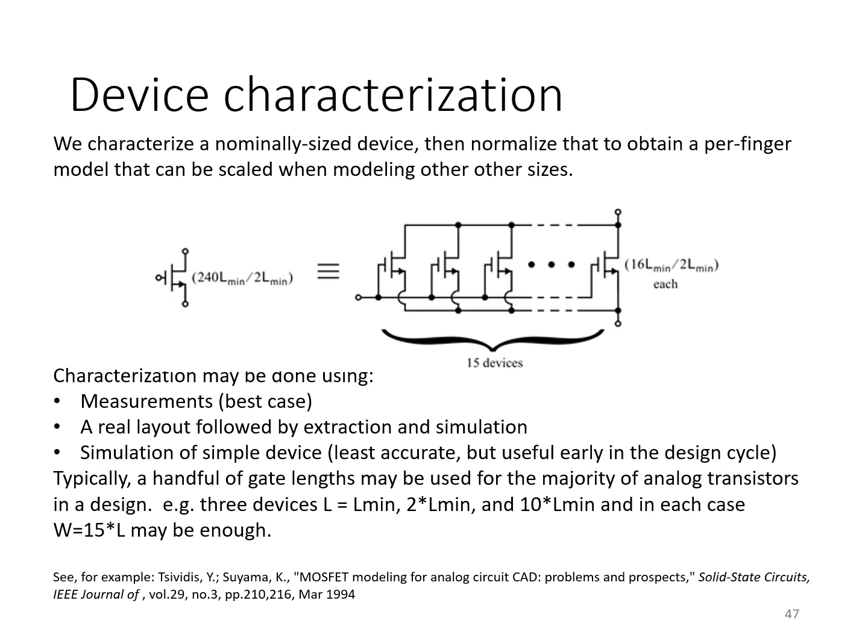to find things like the parasitic capacitances of it, estimate a value for mu NC ox for it, and all the other body effect parameters, whatever it is you might be interested in, threshold voltage and so on. And then if in my design I'm going to end up having a transistor that's maybe twice this size, then I can just apply twice this width, but the same gate length. I can just apply the same transistor parameters, but doubling those that are proportional to W over L, such as